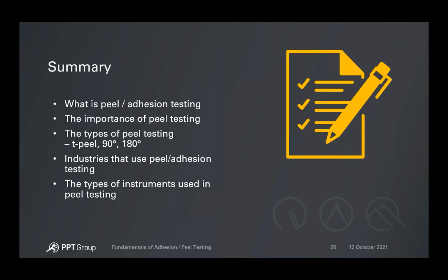And that is to identify the ideal strength, determine the pass or fail limits, and then test for it throughout the production process. And we also discussed peel testing to characterize adhesion in different industries. We then talked about how peel adhesion testing is done, namely how to determine that ideal strength using Goldilocks rule. And finally, we considered the advantages and disadvantages of the various tester types, the handheld, the digital force gauge, the motorized force tester, and software-driven testing solutions.